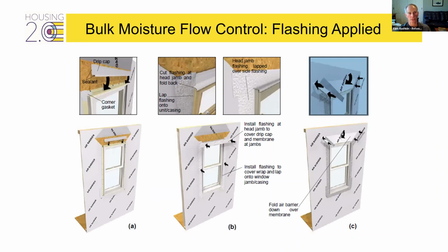You have the flashing above the window, goes above the flashing around the window, which goes over the flashing on the side of the windows, which goes over the flashing at the bottom of the window, which is a pan flashing because we know 100% of the windows leak. When we put the window in place, we make sure when we have sealant, we don't use sealant at the bottom edge of the window so that the pan flashing can drain to the drainage layer that's called the weather resistant barrier that's on the sheathing. It's just shingle fashion taking the moisture off the assembly.